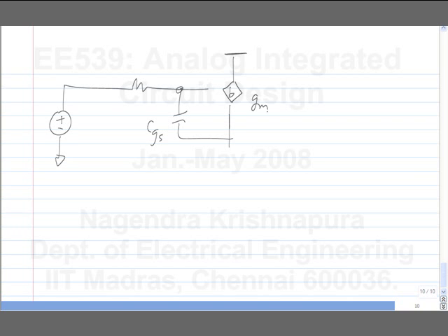Okay. Looking here, it looks like an inductor. And in fact, this is also used in some cases where you want an inductor. If you want to wind an inductor, first of all, you can wind very small values, of the order of 10 nanohenries or so, on a chip. But if you use this inductor, the value is related to Gm and Cgs. By changing the bias, you can potentially change the inductance value. So in some places where you want inductors, but the signal swing is small enough so that the small signal analysis is valid, you can use this inductor. Okay.